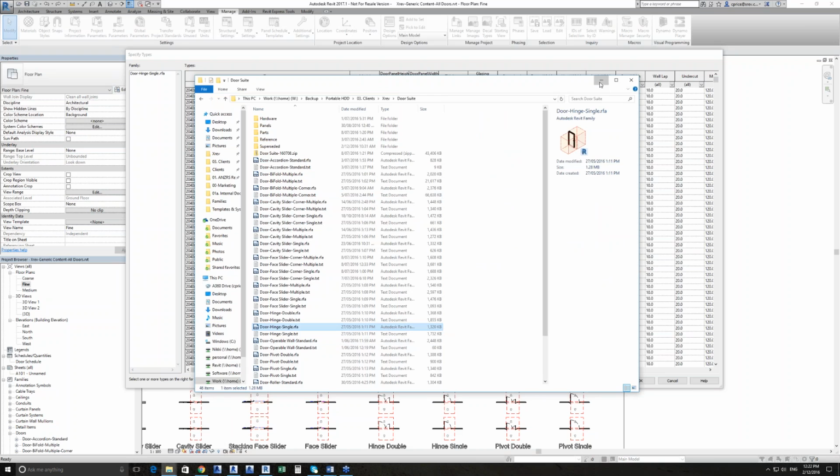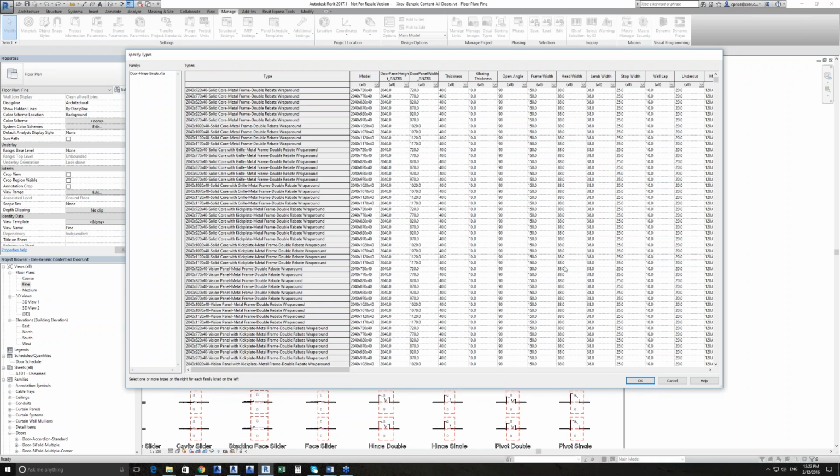That also includes the nested components that go into that. So that's things like the door hardware as well, and the actual 3D clearance zones. If I was to pull those out, the file size would be even smaller. It might be more like 600 or 700 kilobytes. Because they're set up as shared nested components, all the doors actually share those same components. So although when I load this family in, it's saying it's going to add 1.28 meg to my project file size, each new type only adds 4 kilobytes.